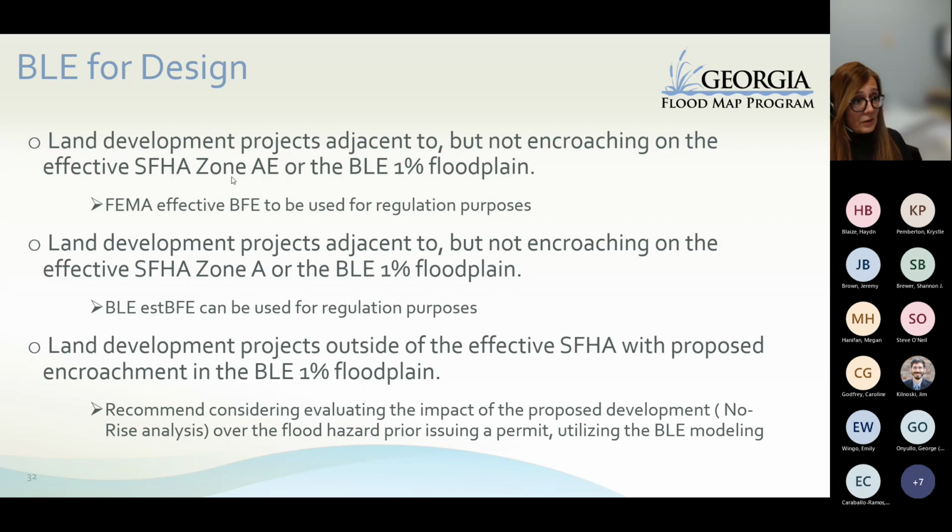So if you have that scenario, again, a property adjacent to the effective special flood hazard area zone AE, we recommend utilizing the effective DFIRM database to determine the base flood elevation.